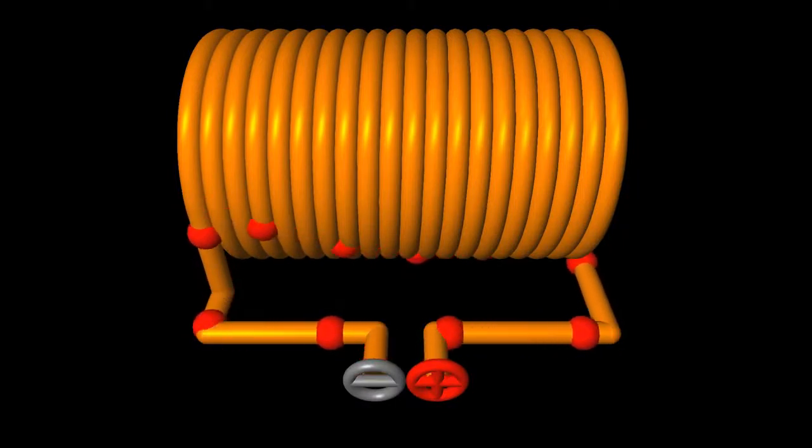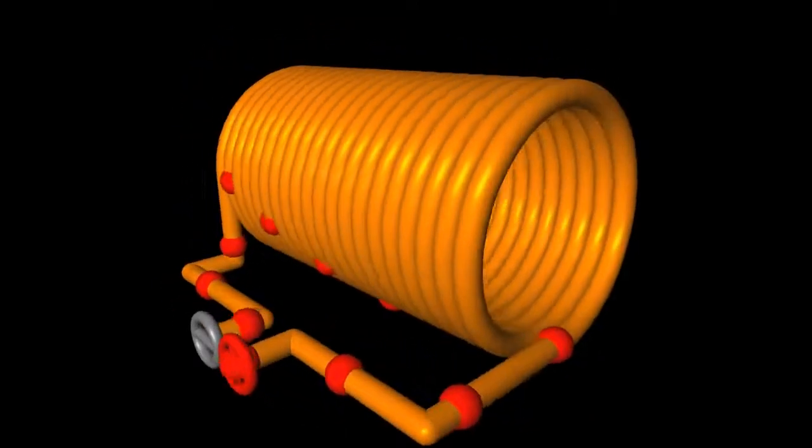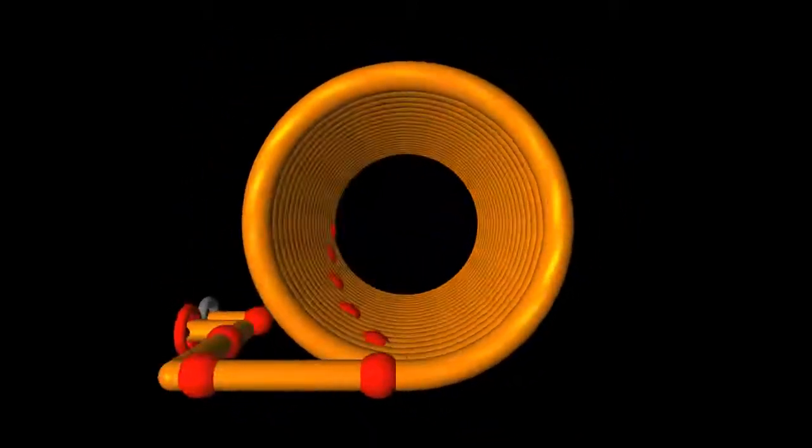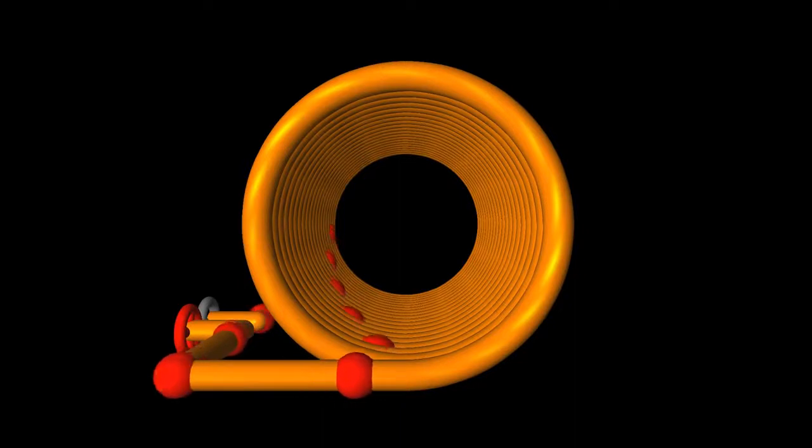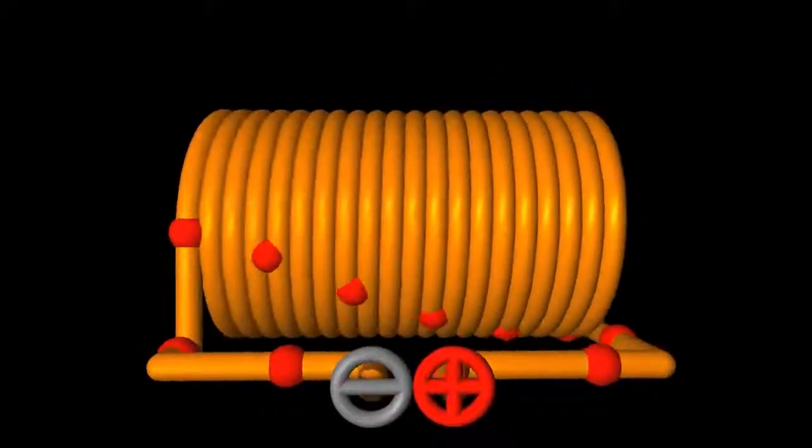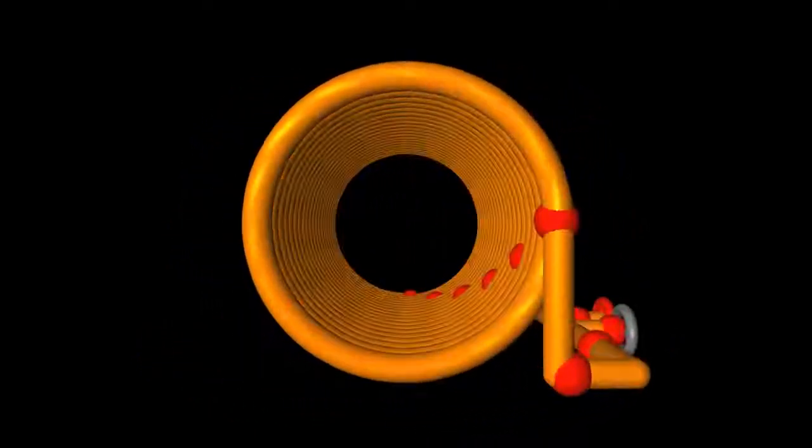The windings of an electromagnet are usually closely spaced, thus a wire with an insulation coating is needed. If you use bare wires, the current will not follow the windings, but will instead cross the solenoid straight directly from anode to cathode, from plus to minus, not creating the desired electromagnetic field.